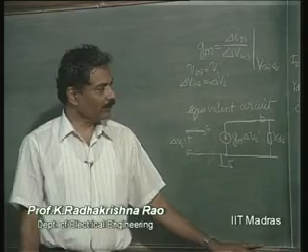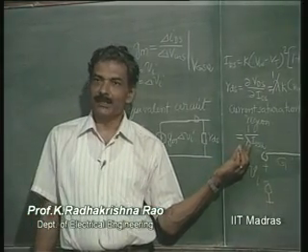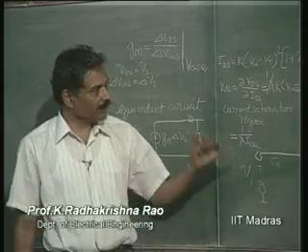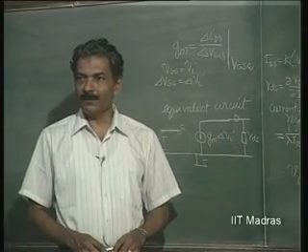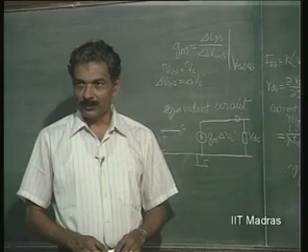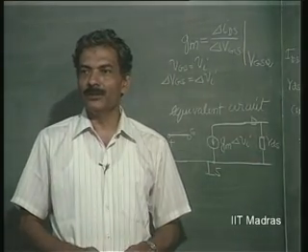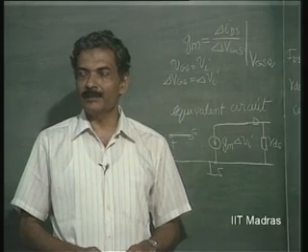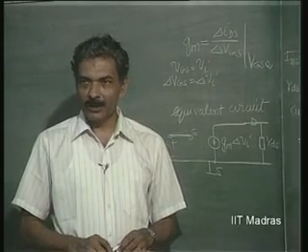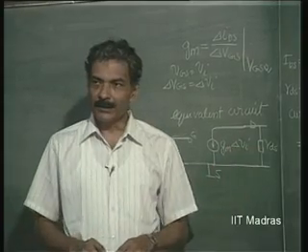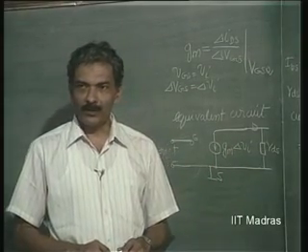This also is an important factor associated with the field effect transistor. What is the order of impedance that it results in? It will be of the order of hundreds of kilo ohms, this RDS, unlike in the case of common emitter transistor, which is of the order of few mega ohms, up to 10 mega ohms.